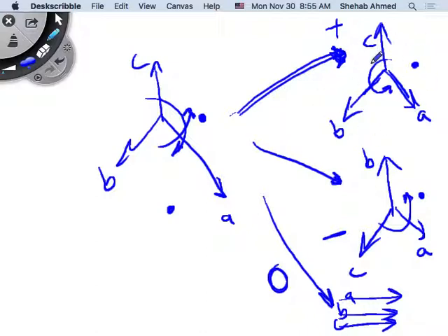motor, applying positive sequence balance, what happens? You produce torque, right? But what happens if you flip the terminals, Dr. Haytham was saying in 338? For those who took 338, it's not a requirement. If you flip the terminals, what happens to the motor in that case? Induction motor. Who took 338? Okay, what happens to the motor? Come on. You don't remember? So the motor will change speed. Will flip. The direction of rotation will flip. It will be the opposite direction, right?